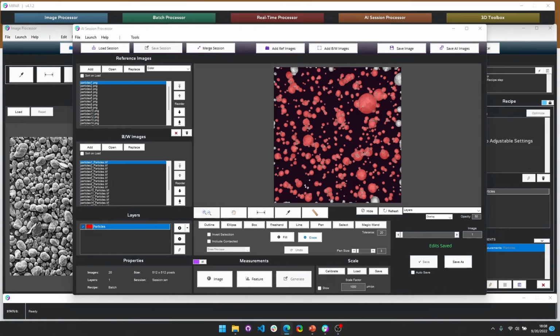And just like that, I have a quantified, repeatable, traceable, and minimum error method to do graphite qualification. Both material suppliers and manufacturers can use this method to qualify their products for sale and downstream manufacturing. Look, when micrograph quantification is this easy, it facilitates further experimentation, like studying particle satellites or understanding the synthesized versus deformed spherical graphite packing density.